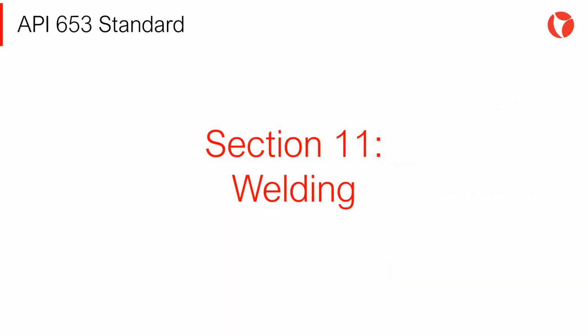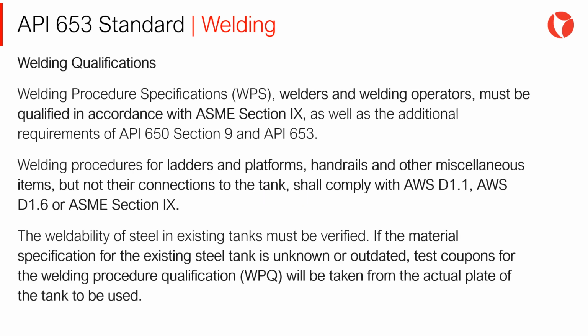Section 11. Welding. Let's talk about welding qualifications. Welding procedure specifications (WPS), welders and welding operators must be qualified in accordance with ASME Section 9, as well as the additional requirements of API 650, Section 9, and API 653.